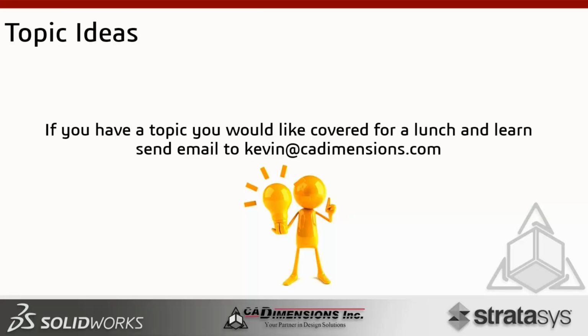First one, can you take an existing BOM table from the drawing and add to the assembly? That is not possible. So this would have to start at the assembly level and be added to the drawing later on. Okay. Next question, publish an e-drawing from an assembly with the BOM table in it. The balloon showed up in the e-drawing, but not in the table. Check the annotations, they are visible. This is something I may have to look at, Matt. I will make note and get back to you. If you could just send me the example at kevin@CADimensions.com.